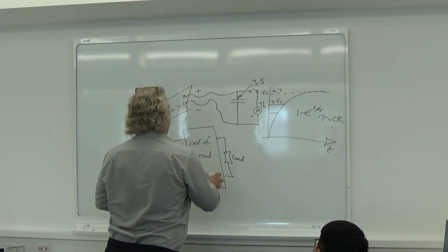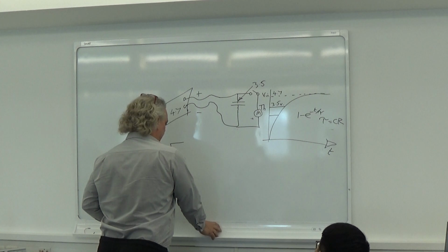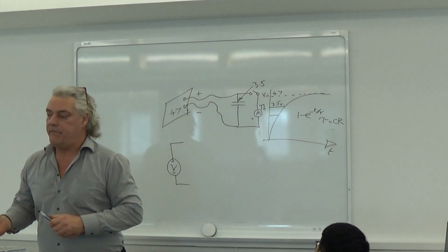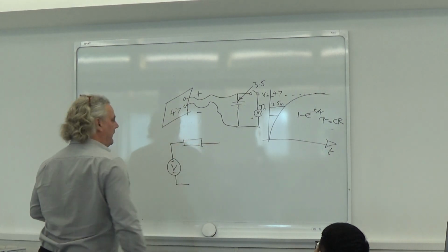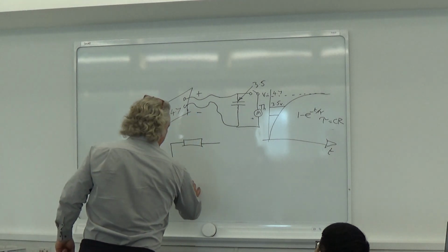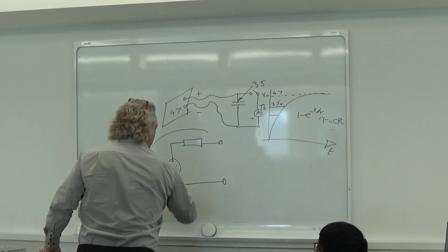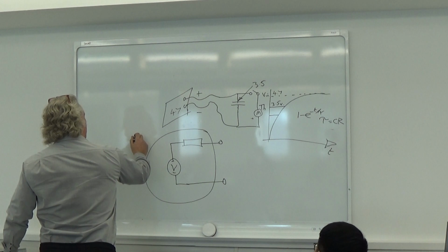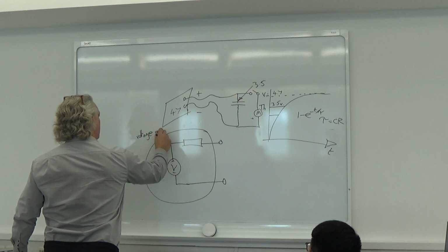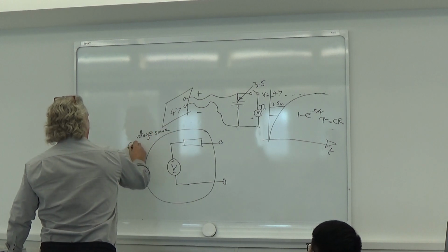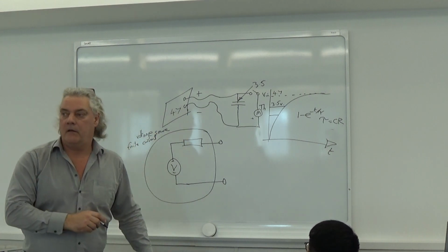So the obvious thing to do there is say, well, this voltage source isn't ideal. We know it's not ideal. So we get an ideal one inside Multisim, but we put a resistor in the way. Okay, that's a completely different ball game now, because what we've now simulated, if you like, this whole thing now is your voltage source. But it's finite current. It means that the current is limited by that voltage source.